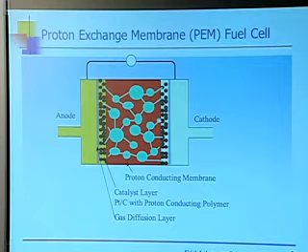So one of the important aspects of this material, besides the fact that it obviously allows protons to transport, is that it's fairly mechanically robust. Not ideal, but you can make these fairly thin films of this material, and it doesn't fall apart on you. The second attribute is that the Teflonic regions are okay, not perfect again, but okay, at making sure that the hydrogen you're going to put on the cell stays on one side of the cell and the oxygen on the other side. There's a fair amount of crossover, especially as the material gets thinner, but it does a decent job with regard to that.